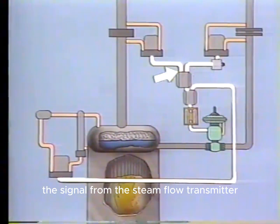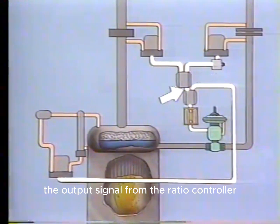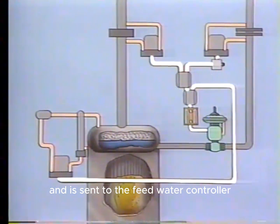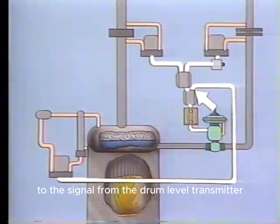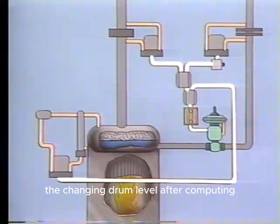The ratio controller computes the ratio of the signal from the steam flow transmitter to the signal from the feed water flow transmitter. The output signal from the ratio controller reflects the change in the feed water flow and is sent to the feed water controller. The feed water controller compares the signal from the ratio controller to the signal from the drum level transmitter. As you recall, the signal from the drum level transmitter represents the changing drum level.